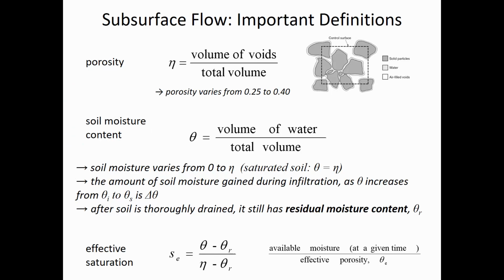So just as a refresher, remember that under the soil we have voids that are containing some water and some air. This illustration is showing that we have solid particles that are covered by a thin layer of water, and then in the space between those thin layers of water, the air exists. And the smaller the grain, the more tightly bound the water will be to the solid particle, and the higher the suction or the tension will be when we have unsaturated conditions.